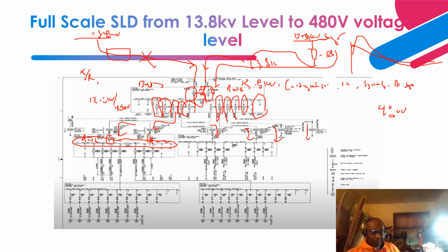As you can see over here, we have a feed from different sources. This feed is coming from this bus, then another feed is coming from this other bus. So if this bus should be faulted, I can have a reliable bus feed coming from here. Then all I need to do is close the tiebreaker.